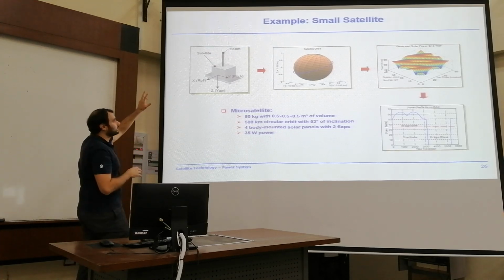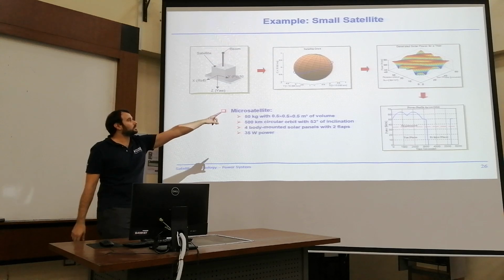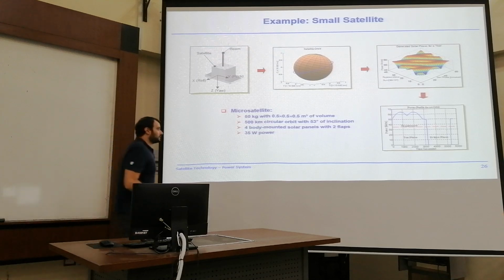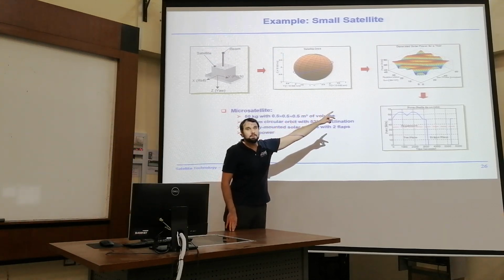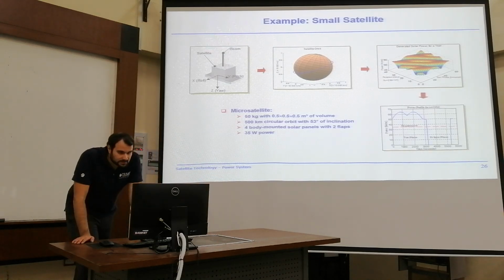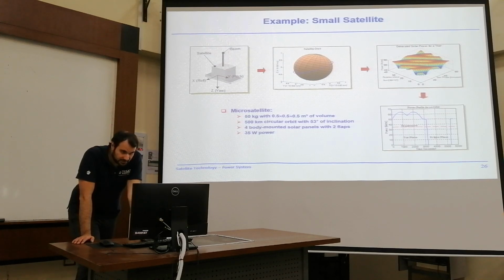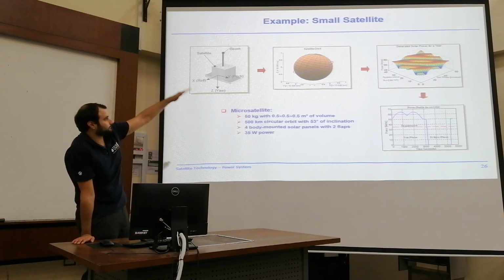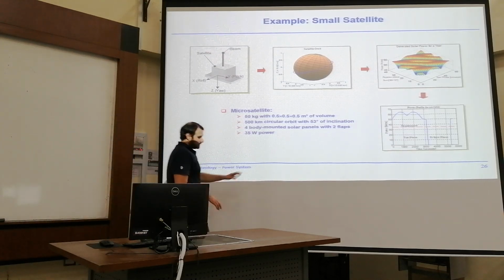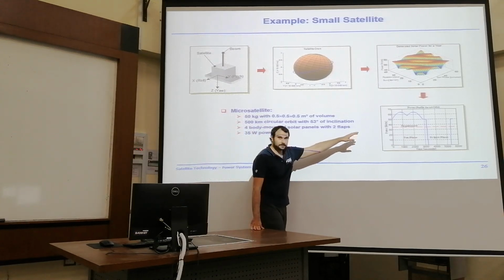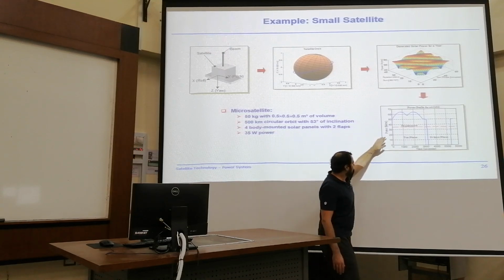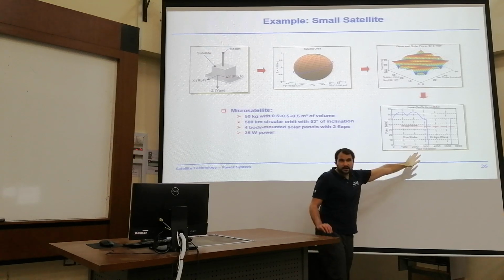With the satellite orbit and your design, you can have a graph and check on the generated solar power for one year. And you see, this is anything but linear. It's fluctuating over the year in many dimensions, not just for the sun phase, but also for the rotation and the total power output. And you can see down here on the lower right, our required power is about 35 watts. And we have the sun phase and the eclipse phase.